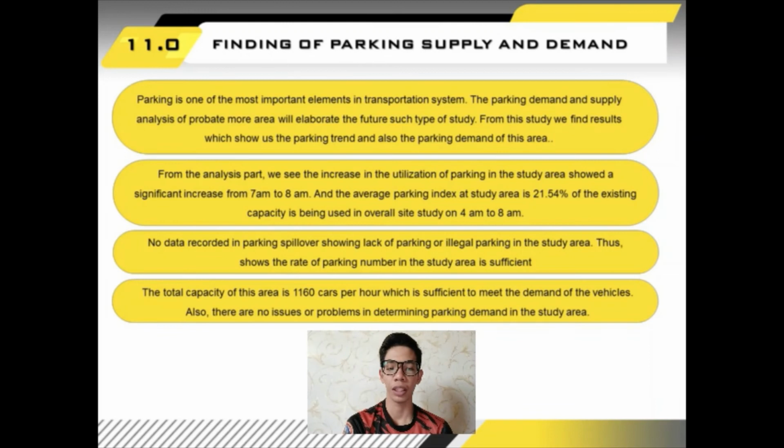However, the use of parking in the study area has not yet reached a quarter of the total number of parking lots. Besides, the average parking duration of the study area is 3.28 hours, and the average parking index at the study area is 21.54% of existing capacity being used overall from 7 am to 8 am.